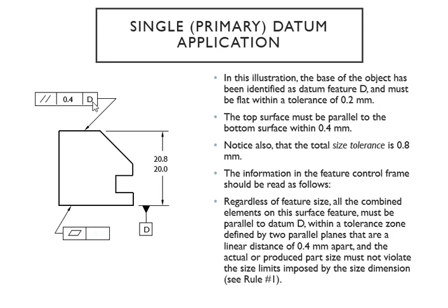Okay, and here is your 0.4. And you have the datum. There's only one single, so that's your primary, which is on the surface. And of course your dimension, you can go from your lower limit of 20.0 to 20.8, so you have about 0.2. We're dealing with millimeters because you see the 0 right in front of the decimal. So I know that I'm not in inches, I'm in millimeters, so 0.2 millimeters. So that's your flat plane right there for primary datum. And this is your tolerance, and you can vary in between 0.2 millimeters for that.